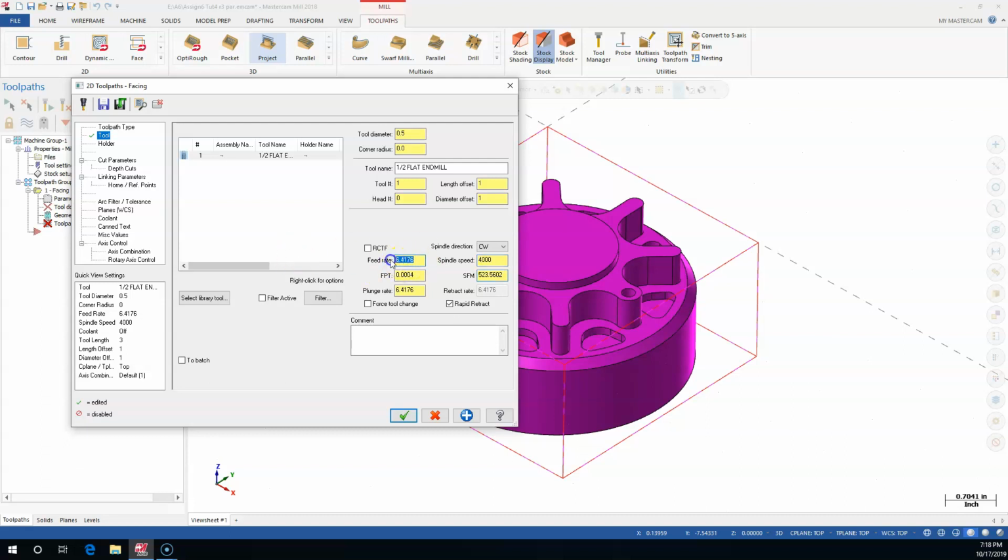And I'm not sure, like I said, if we run this in acrylic, my thought process, if I run this in acrylic, I will have a nice smooth surface, or at least a clear surface on top. And so the face operation, I will note this as optional. I may come back and suppress this out, tell it not to post. And if we're running it in aluminum, I would like a nice shiny surface there.